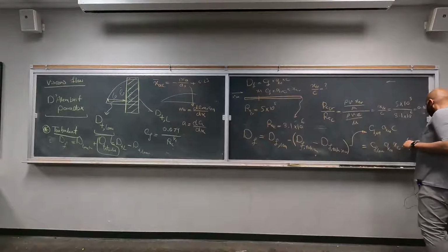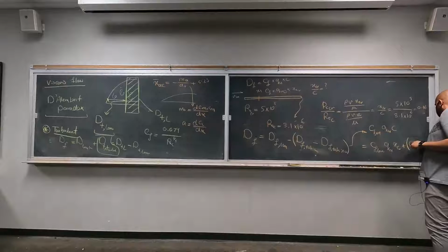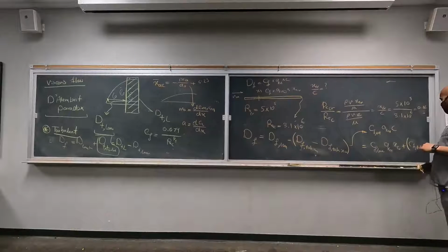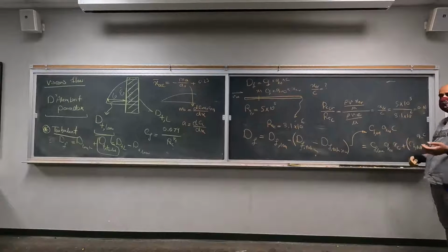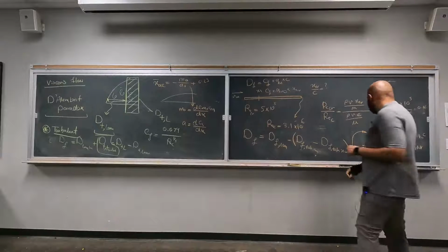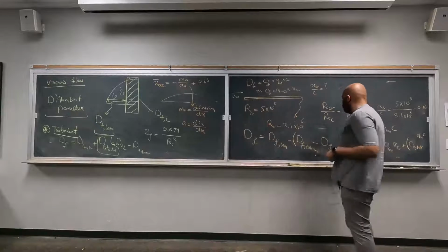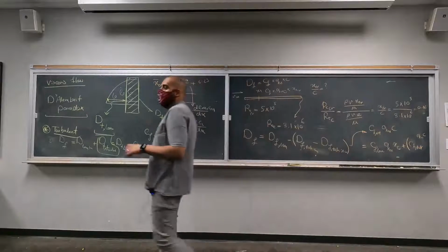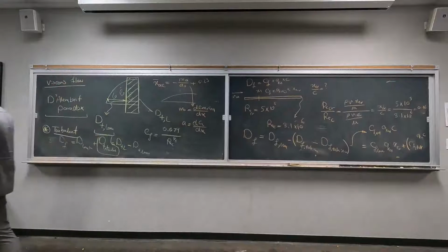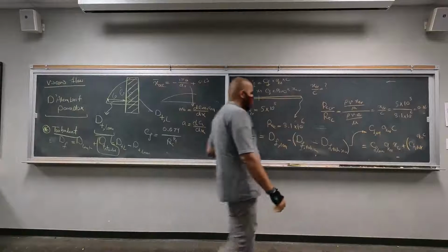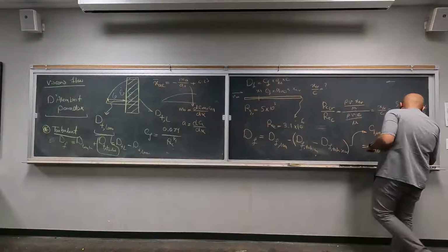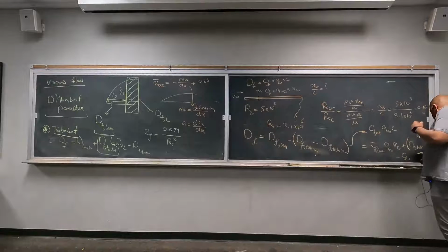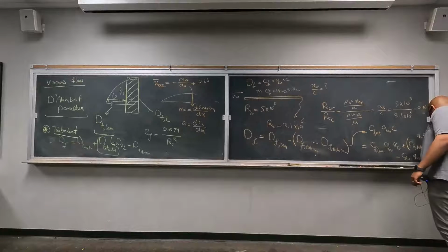Drag force, assuming that all of the plate is turbulent. So CF, assuming all of the plate is turbulent, multiplied by Q infinity, multiplied by the length of all of the plate, which is C, minus the drag force, turbulent drag force of the laminar region, right? We want to take that out. So CF, turbulent and laminar, whatever, Q infinity, x critical.